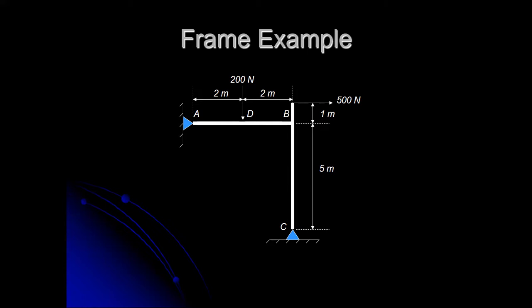Well, we've seen that we can handle 3 unknown quantities. When we did method of sections, we had to make sure our cut through the truss only went through 3 unknown members, because our setup and our equations of equilibrium could only handle 3 unknowns. That we have 6 unknowns here means that we're going to have some issues with our equations. Whenever you have more unknowns than you have equations, what it tells us is that we're not going to be able to solve the equations right away.